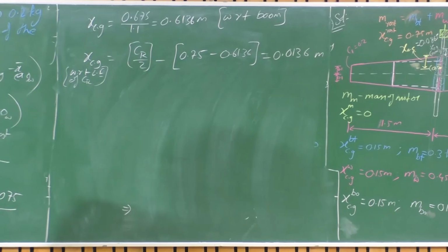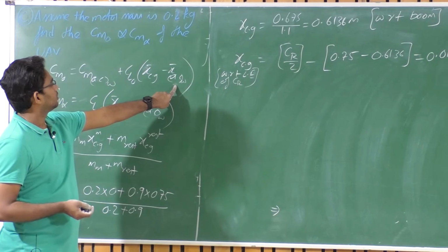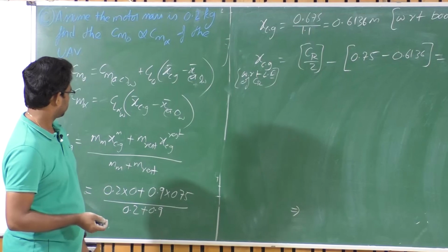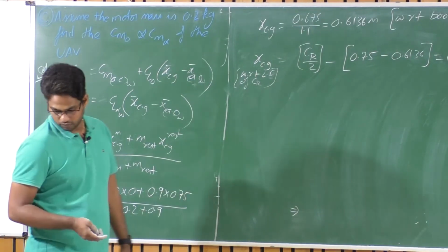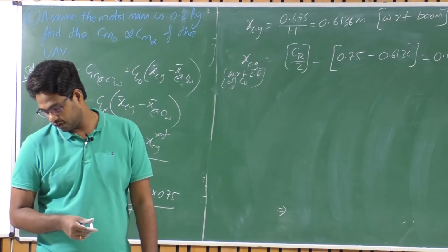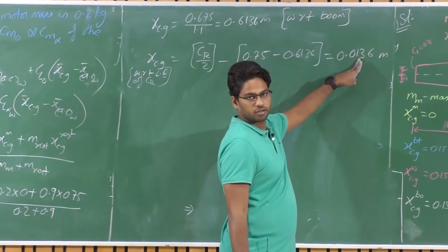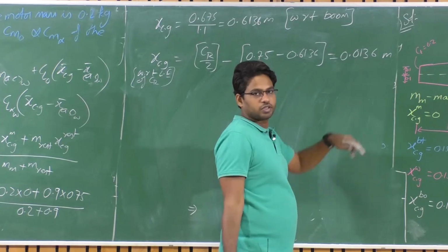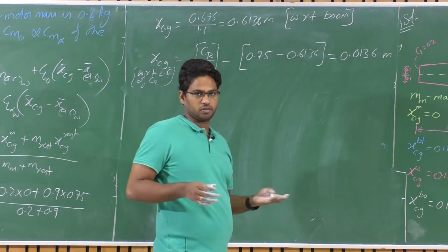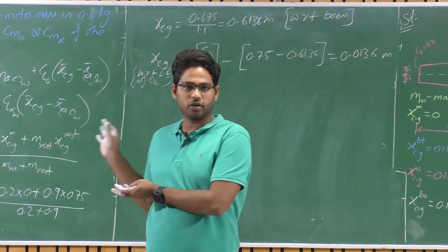And my aerodynamic center with respect to that is about 0.0865 meters, which is 8.65 centimeters. The CG is 1.3 centimeters behind the leading edge, and the aerodynamic center is 8.6 centimeters behind the leading edge. So the aerodynamic center is behind the CG here, correct? In that case, we have Cm alpha negative, and we'll see whether Cm naught is positive or not.